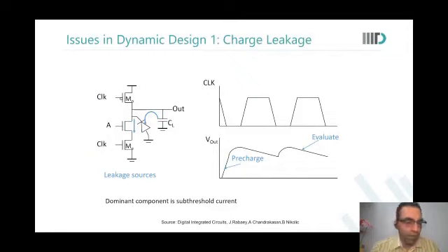So one another important issue. We talked about the floating output. So why is that an issue? That is an issue because there is this diode leakage over here. Due to this, you wanted the output to remain 1, but it is floating. Due to this leakage, this output will discharge. Yes, sir. And this then needs to be restored. There is no way to restore this.